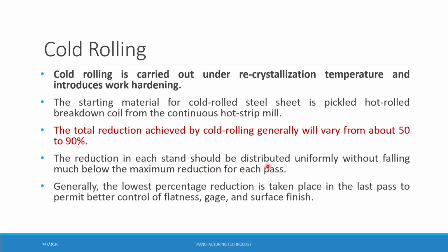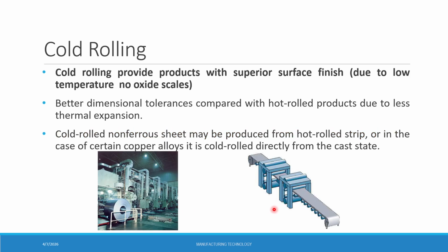The reduction in each stand should be distributed uniformly without falling much below the maximum reduction for each pass, and generally the lowest percentage reduction takes place in the last pass to better control the flatness, the gauge and the surface finish of the materials.